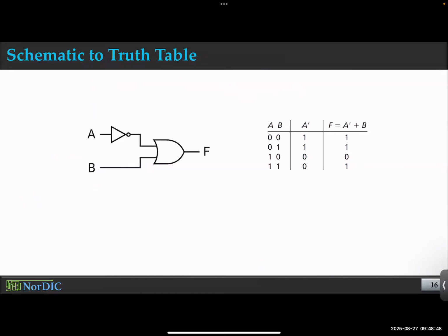All right. One other quick example of how truth tables are made is we can look at a circuit and then create a truth table for that circuit. And one approach is just look at how many inputs you have in the circuit. 2, A and B, and this is your output. These are 2 original inputs. So your truth table will have 2 columns.